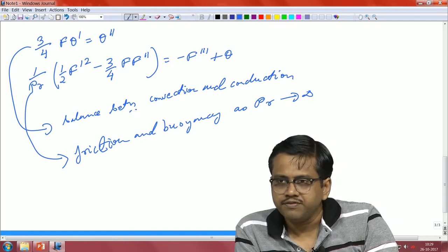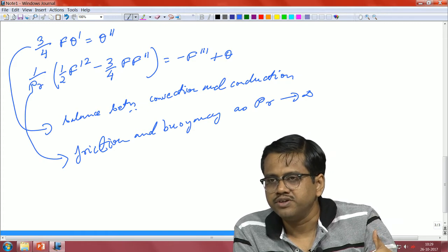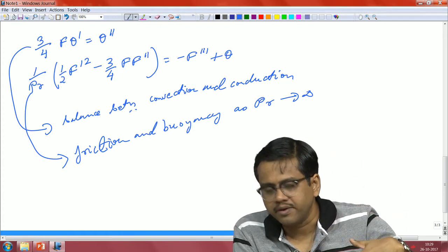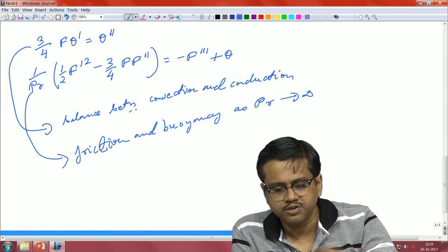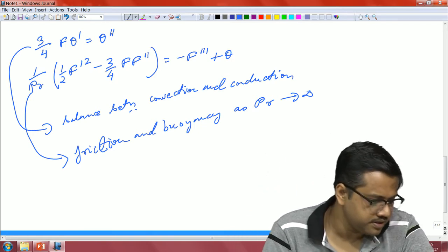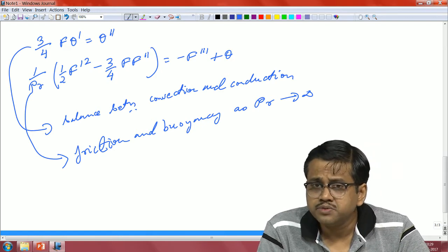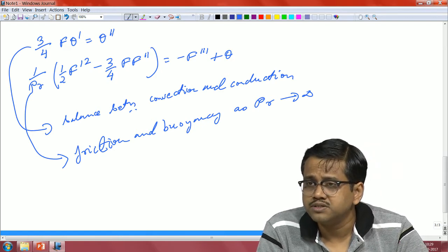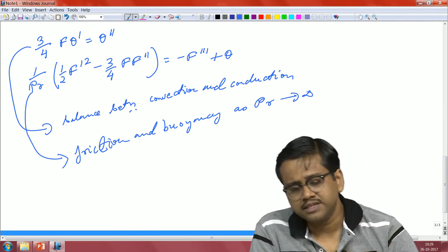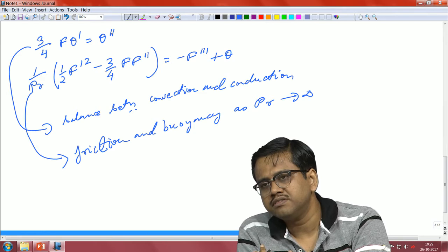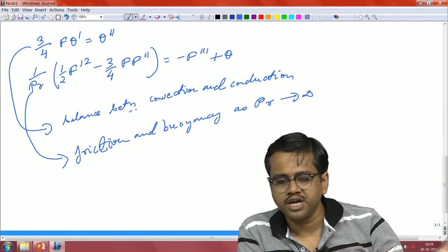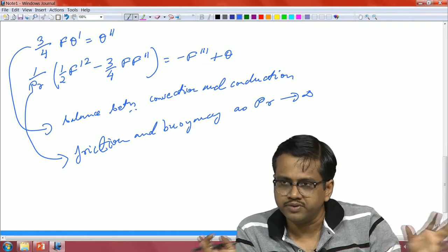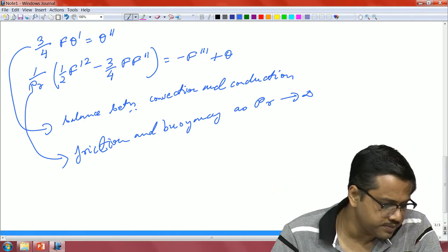on that left hand side, Prandtl number is there in the denominator. So, it will be 1 by infinity, right. Okay, so, this part will just basically vanish, the left hand side. So, it will be a balance between the other two terms, right. So, this also agrees with what our scaling argument initially was, where we said that if the Prandtl number is very high, it is a balance between friction and buoyancy, right. If the Prandtl number is very low, it becomes a balance between the inertia as well as the buoyancy. Buoyancy will be always there, if you recall those expressions.